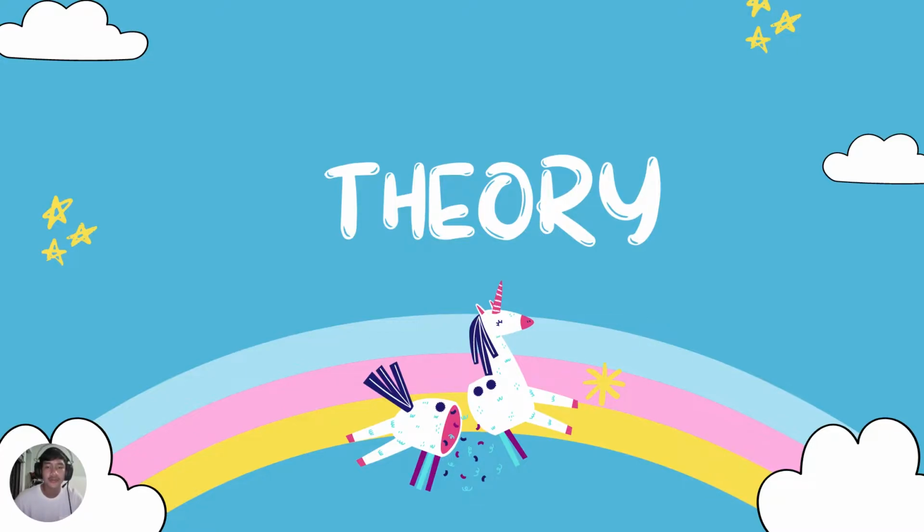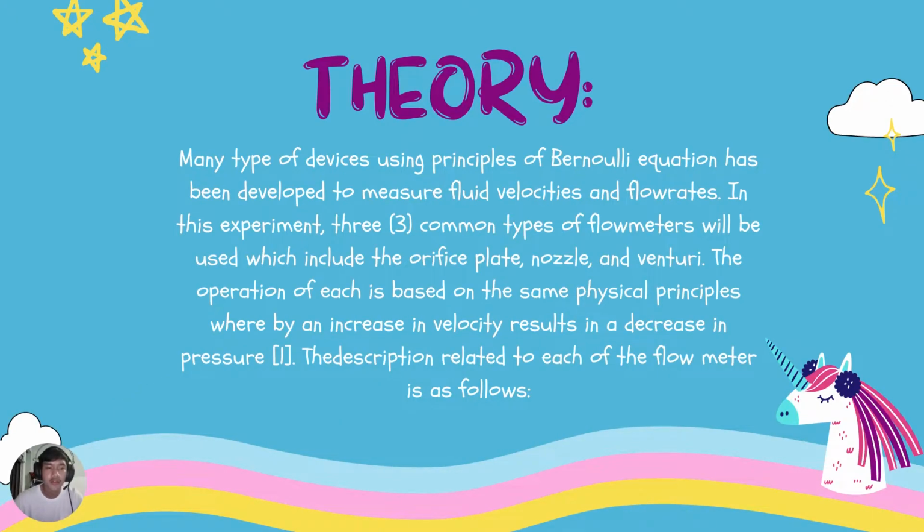For theory, many types of devices using the principle of Bernoulli's equation have been developed to measure fluid velocities and flow rates. In this experiment, three common types of flow meter will be used, which include the orifice plate, nozzle, and venturi. The operation of each is based on the same physical principle, whereby an increase in velocity results in a decrease in pressure. The description related to each flow meter is as follows.